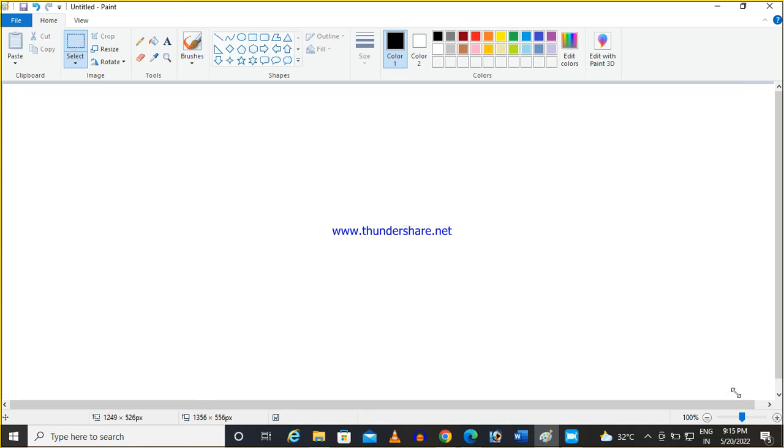So this is all about how to select the resistance, and accordingly you can set the power rating of the resistance. Power is I square R. So how much power you need, and for what time, it's not continuous, you can find out to reach that V by 3 what should be the time, and during that time only it will flow that 5 ampere. After that it's not continuous rating, so the size of the resistor also will reduce. So this is the way to calculate the precharging resistor. Okay,